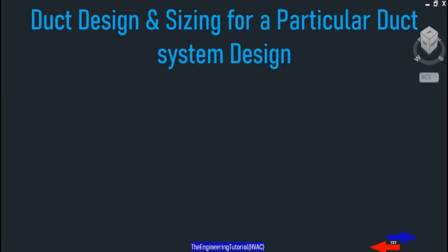So for all the sizes indicated on the duct sizer, you need to add 3/4 inch to the round sheet metal duct size in order to get the right size for the flexible duct, which is a compression of 4%.